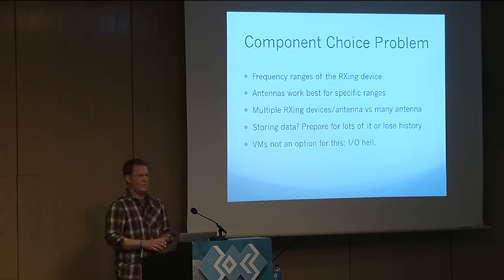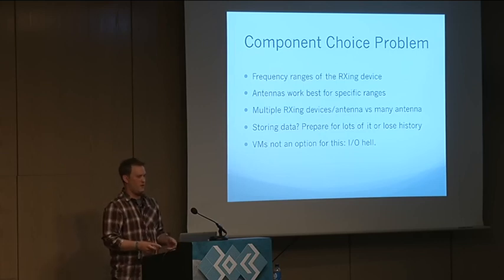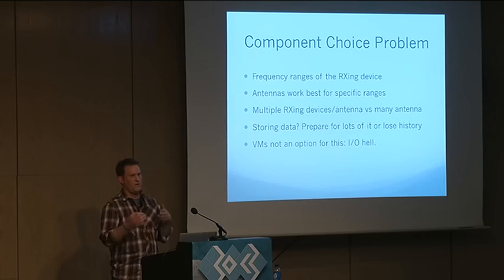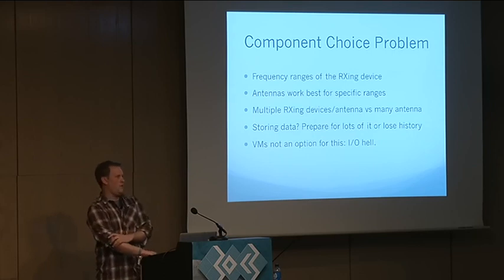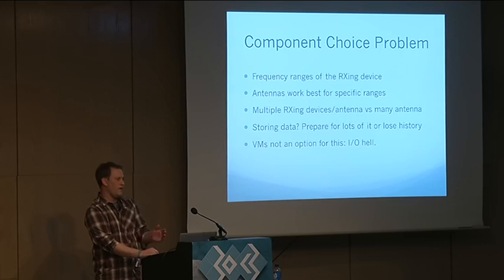And I just wanted to introduce it early on because it's fairly important. Most receiving devices have a fairly limited range in terms of frequency width, bandwidth. For example, if you look at the Osmocom HackRF, you're maxing out at 20 megs of bandwidth there, but you're not even going to get that because of the limitations on the USB bus. And so you kind of need to be worried about the device capabilities that you're purchasing.